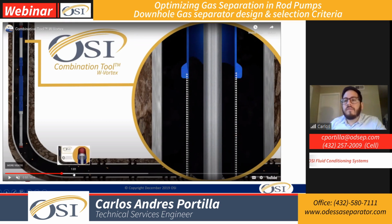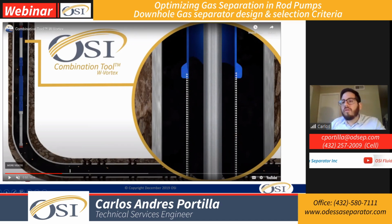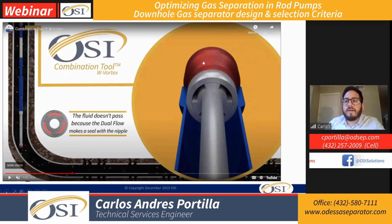If we don't have as much sand, or if we're not worried about sand, we can make these slots bigger, which helps more with the coalescence effect for the gas bubbles, or we can go smaller and start filtering that sand. Here we have our dip tube head, which basically prevents the fluid from flowing through these slots.